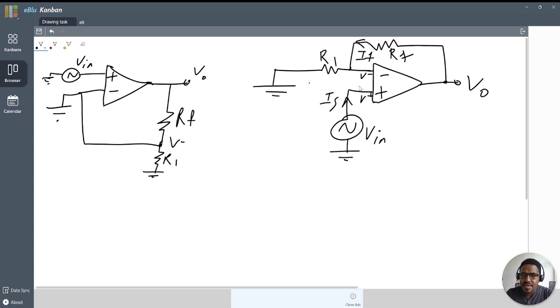As you see in the circuit, our input is in the non-inverting terminal. The inverting terminal becomes grounded. The feedback goes to the inverting terminal. Look at the left figure also, that is the same as this circuit. Only to clarify the voltage divider for the inverting terminal: the positive on the upper side is our V in to the non-inverting, the inverting is below that, the inverting terminal. So the feedback resistor goes to the inverting terminal.